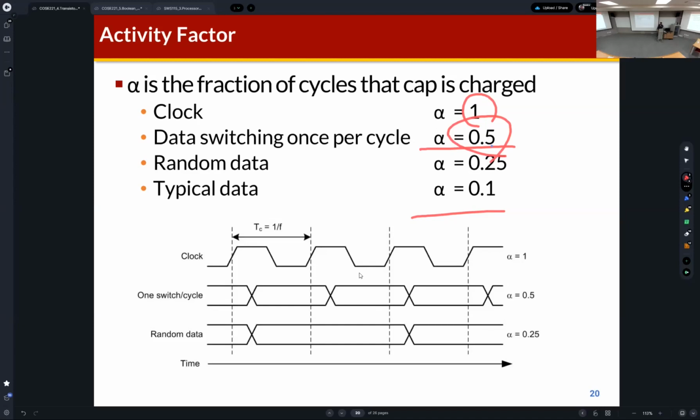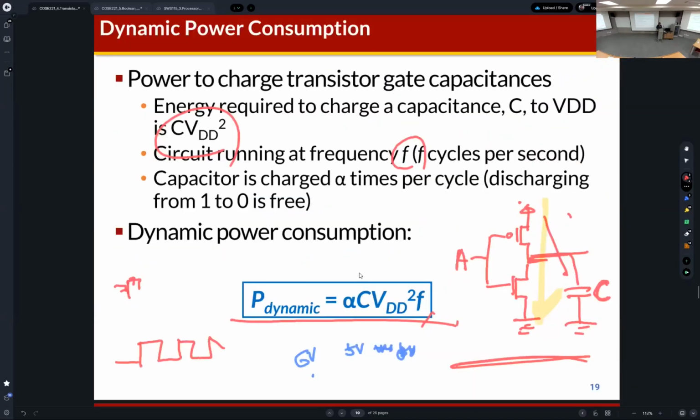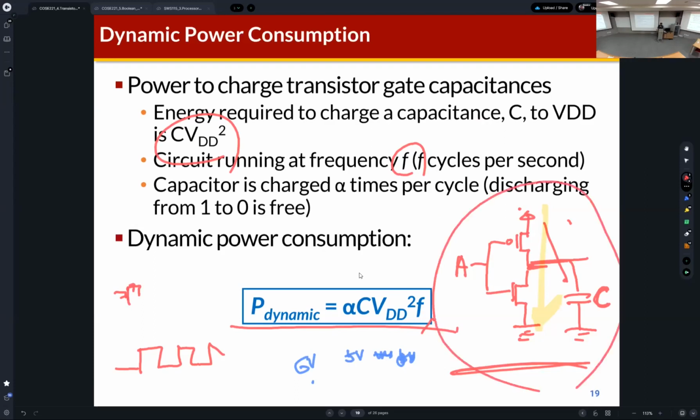When the signals change, we already learned how to implement the basic CMOS circuit like this, using PMOS transistors and NMOS transistors. If input signal values change, then output signals can also change. When the signals change, electric charge transfers through this network, so this circuit consumes dynamic power.